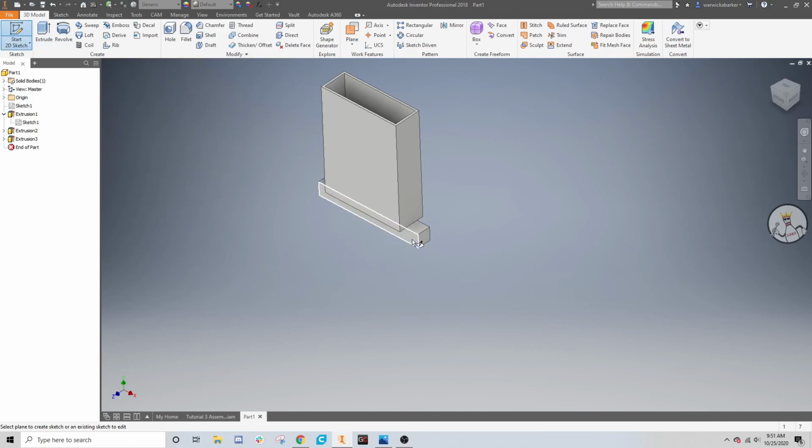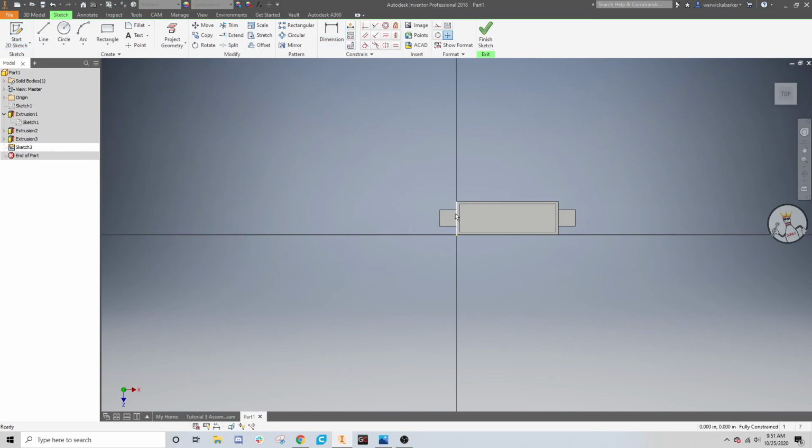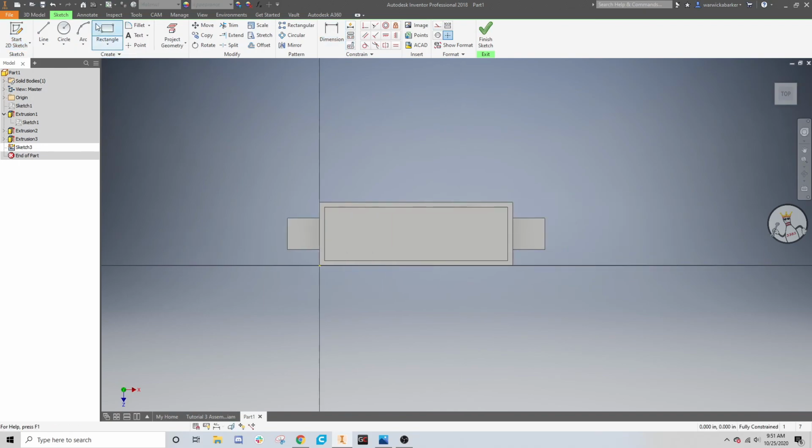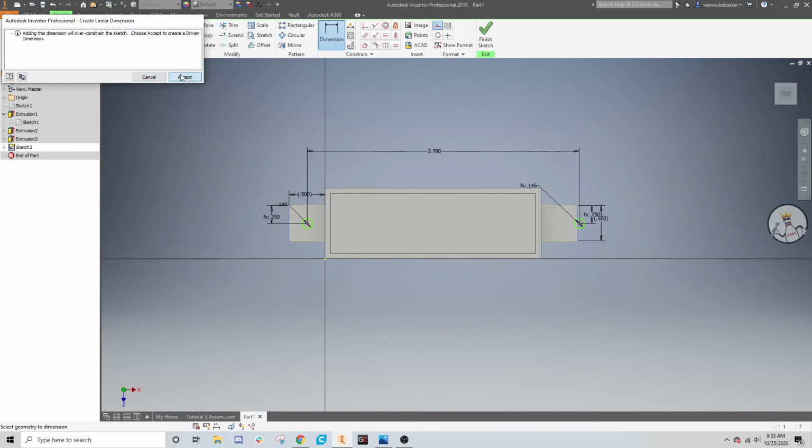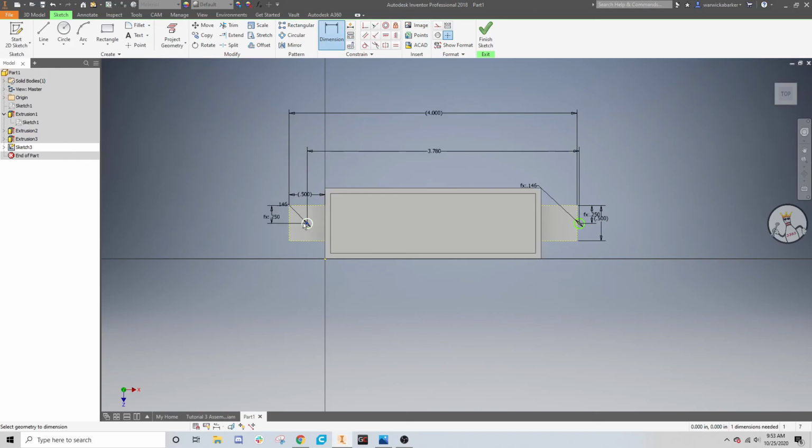And now we want to put 2 holes on these sides so we can attach it to the channel on the robot. So we're going to click here and here, and we're going to use our project geometry and construction line tools again to help us dimension the location for these. And then what's the distance between here and here? Oh, it's that. Okay. And then click on the center dot and this line. Click somewhere above or below.